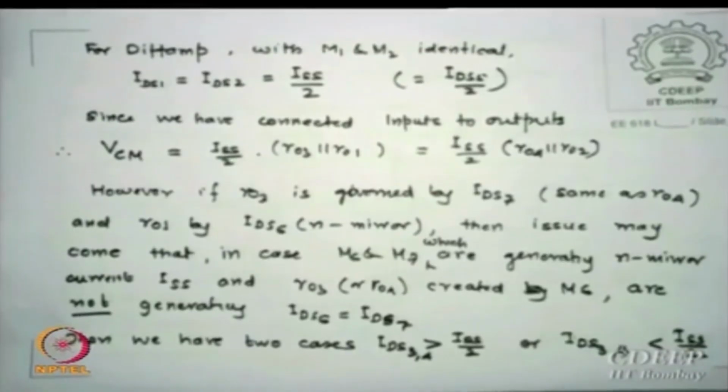But what is the problem? Cost, you pay extra for that. I have already shown you that a fully differential stage can always be used as single ended: look at the single end only and do not worry about the other one. So there is no issue if we really use this as a single ended amplifier.